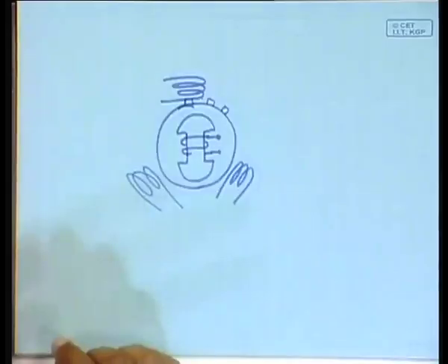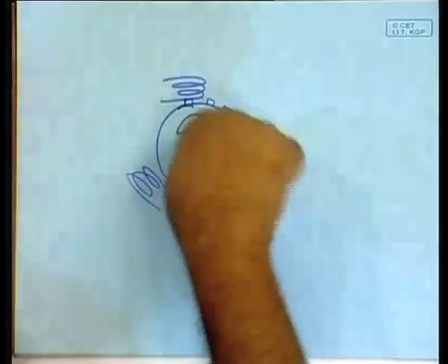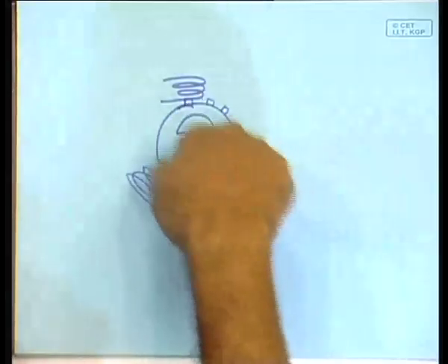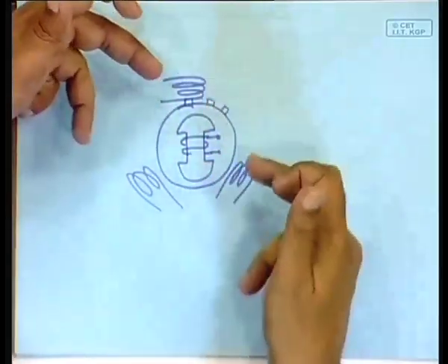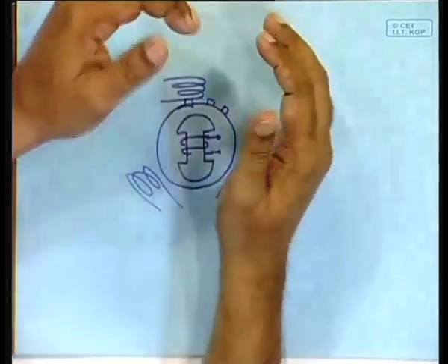What will be the speed or frequency of that sinusoidal voltage? It is exactly proportional to the speed. Okay. So, it will have to be rotated at a speed that will be able to generate, for example, our supply is 50 hertz, it will be able to generate 50 hertz.